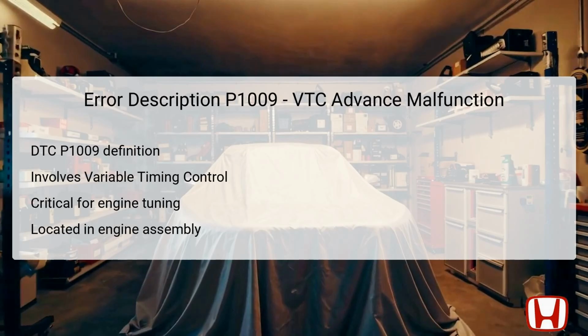Failures in these parts can often lead to oil control issues within the VTC system, which can trigger this error code. Understanding the location and function of the VTC components is essential when diagnosing code P1009, as effective repairs depend on identifying the root cause within the system.